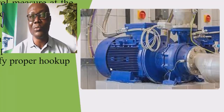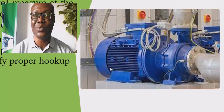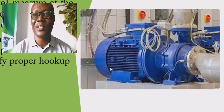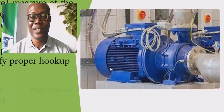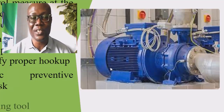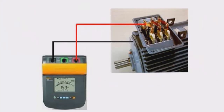Then during installation too, we can also carry out insulation resistance tests to ascertain that all the electrical components and assets that we are installing will be able to withstand the voltage pressure that they will be subjected to. They will not result in insulation failure and thus liability problems in the course of use. During periodic maintenance, as we outlined earlier, you can also carry out insulation resistance tests. And also when there are problems, trying to determine the cause of the problems, you can carry out insulation resistance tests.